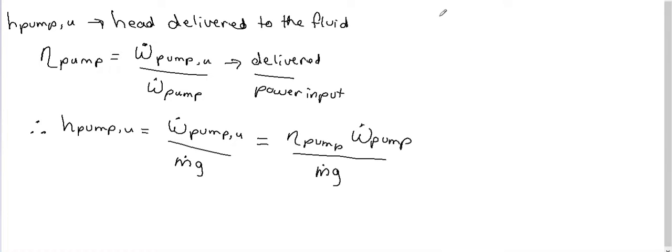Well, it's simple, m dot, the mass flow rate. So when you have a fluid that's flowing through something, you're going to have the mass of it and how much of that is going per unit time. So in other classes or other places you might have seen this dot here, and that is with respect to time. So it's the time derivative of a variable. So for example, just for your reference, if you have x dot, that's actually just dx by dt. y dot would be dy by dt.